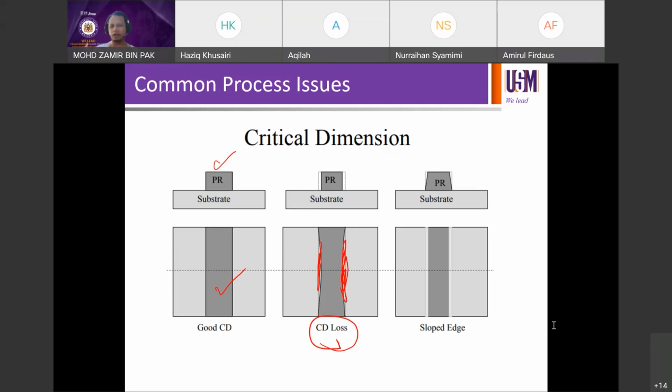Okay, is that clear? When you want to troubleshoot a problem, it starts with problem identification. I want to teach you everything in one go. You have to be clear on what the problem is before you do anything, before you start your thinking, before you consider the potential solution. The boss will ask first, what is the problem now? CD is too high. Why is it too high? I suspect energy dose drifting. Why is it drifting? Then you have to go back to the 5 whys analysis that I taught you last week, I think. So now the issue is CD on the high side.